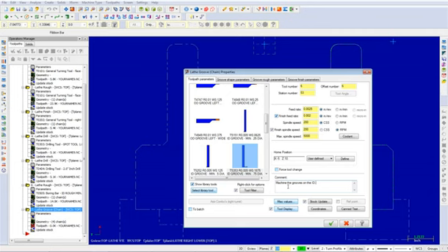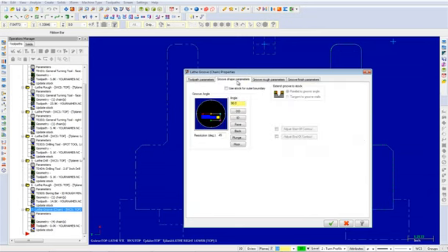From here, choose the Groove Shape Parameters tab and enable Use Stock for Outer Boundary. This tells Mastercam how to use the stock as the groove's outer boundary. Then pick the Groove Rough Parameters tab.